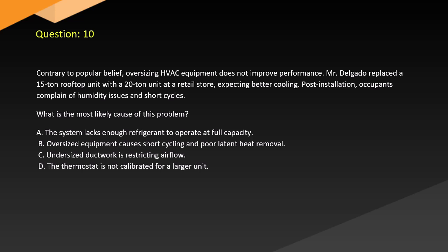A. The system lacks enough refrigerant to operate at full capacity. B. Oversized equipment causes short cycling and poor latent heat removal. C. Undersized ductwork is restricting airflow. D. The thermostat is not calibrated for a larger unit.